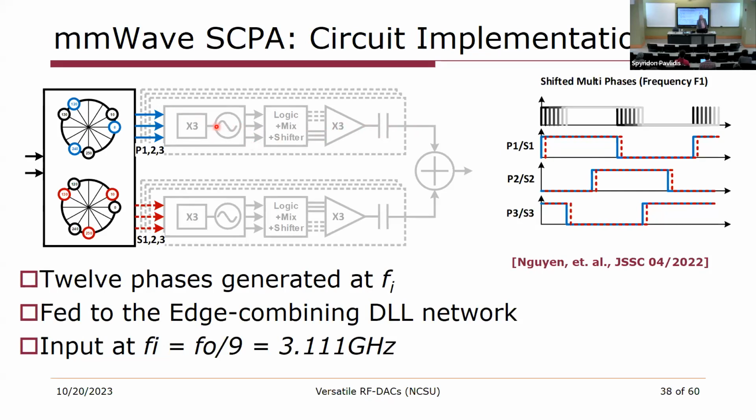We did not think that we would be able to use polar operation because polar operation is fairly wideband. Polar operation is where we encode the amplitude modulation and phase modulation. Here we're going to encode in-phase and quadrature, or Cartesian, modulation into our circuit.